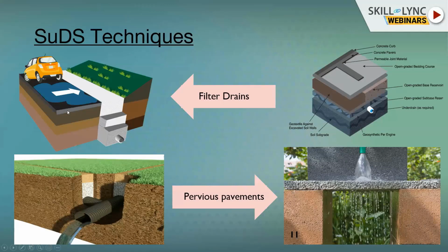So we provide certain solid blocks or porous paving or porous concrete or grass pavers through which the water can infiltrate. If you see in this figure, there is again a sand layer, then the gravels, and then the under drain pipes. And in this image, this is a layer of pervious concrete.